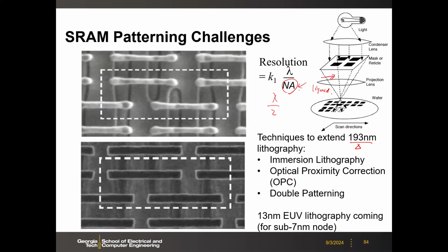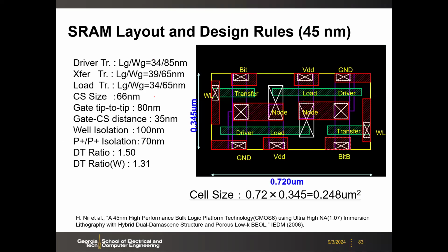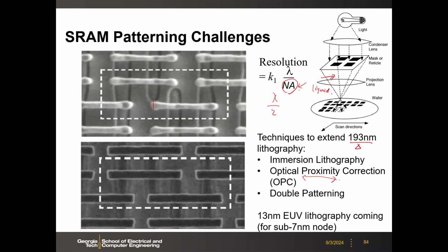And also, this OPC is widely used for computational lithography. So what that means, for example, here, if you do nothing, even though from the layout it is all straight lines, like a rectangle, due to refraction, diffraction, all the optics stuff, after the patterning the photoresist may have a round shape at the end. Okay.